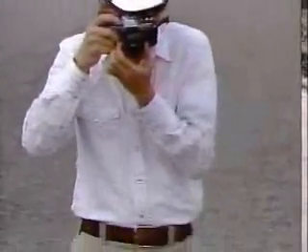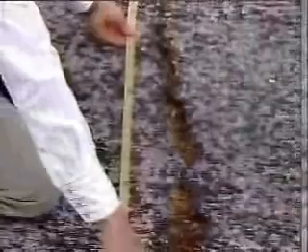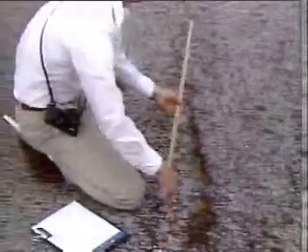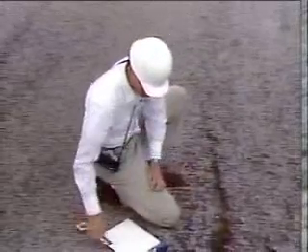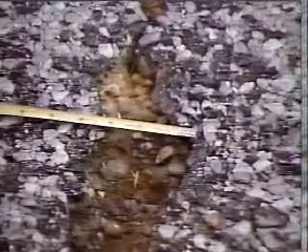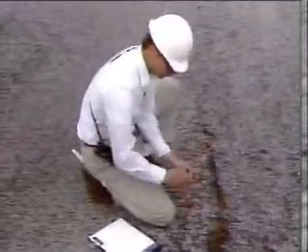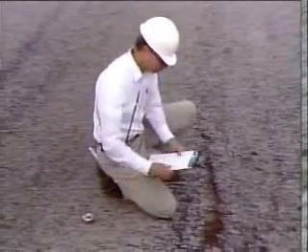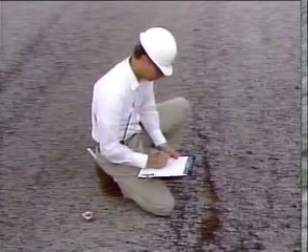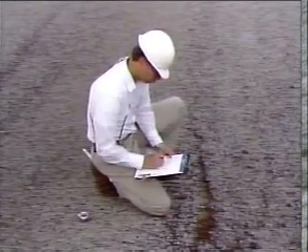For all 3 types of cracking, documentation is a must. Photograph or sketch and record the location, length, depth, and width of these cracks carefully. Consult an engineer as necessary to find out the causes of cracking and what can be done to minimize or repair its impact on the dam.